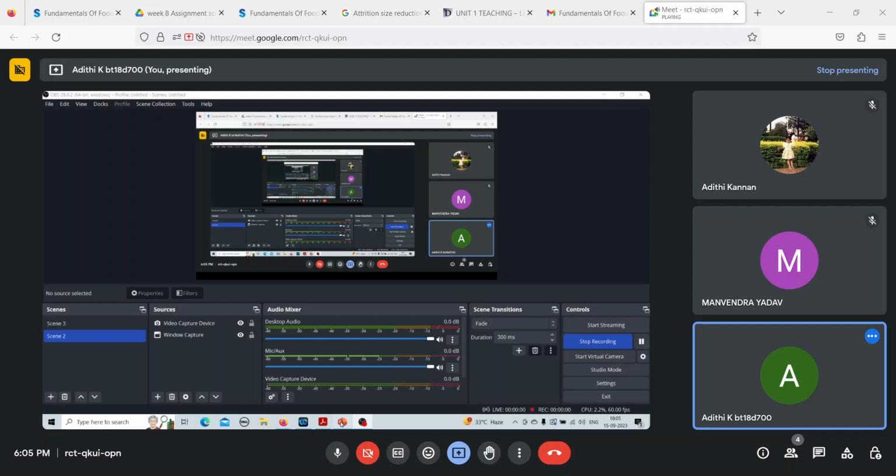Same way, let's say you want the surface volume diameter, so p will be equal to 2 and q will be equal to 3. This is also known as the Sauter diameter, if you remember, the surface by volume ratio. If you substitute p equal to 2 and q equal to 3 here, you will get the formula for Sauter diameter as well. Same way for number surface diameter, you have number, which is p equal to 0, and q is equal to 2. If you substitute it back in the equation, you will get the equation for number surface diameter as well.